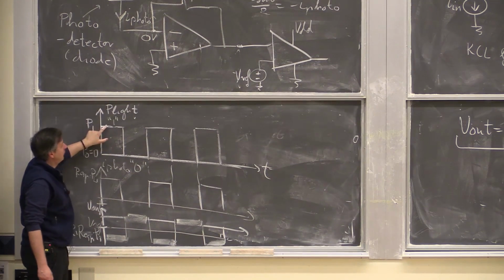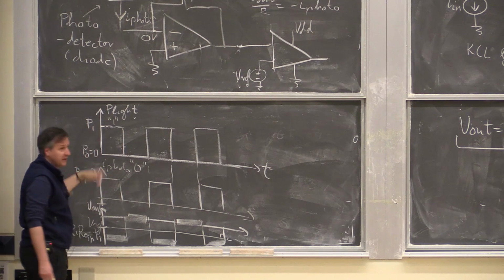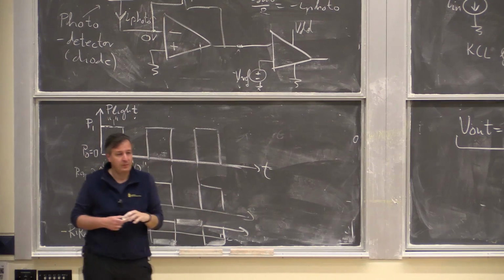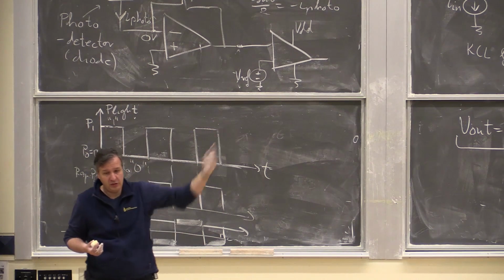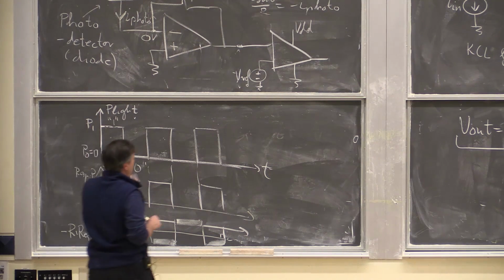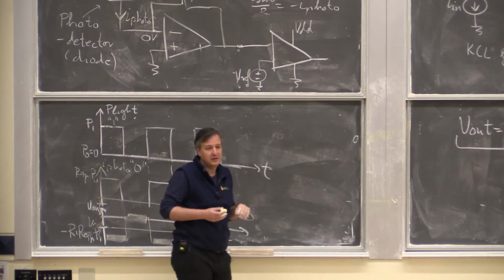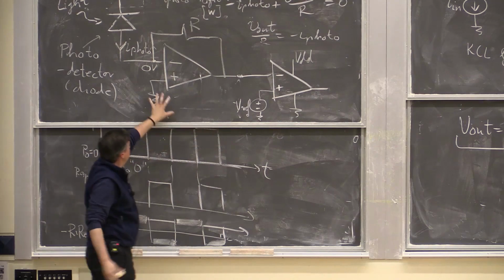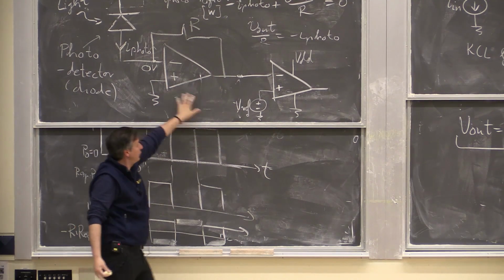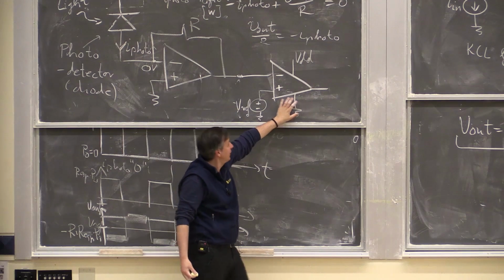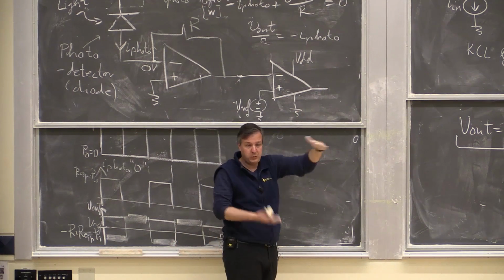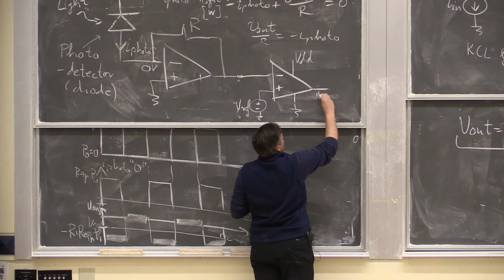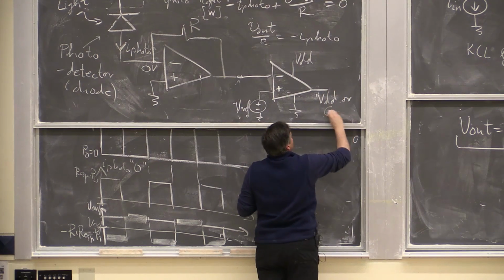So I should get a high level at the output of the comparator. So what sign should I use over here? When input is less than the reference, I want a high voltage. So is the input on the plus or minus? On minus, right? So in this case, this is our optical receiver. This is a decision circuit. This circuit tells us in logic levels, supply or ground, whether we have sent a 1 or a 0, right? So this is a VDD or ground is the output.